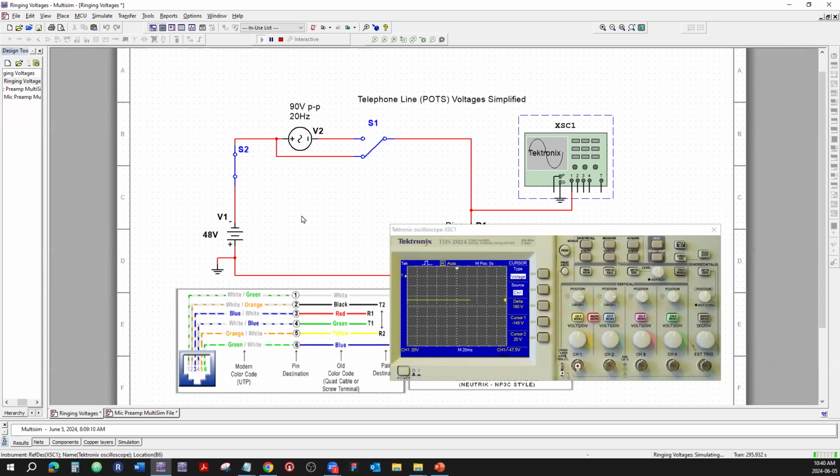So you could make announcements or general announcements using any phone that's connected to the system, just by picking up the handset and punching the feature number or the button that says page, and the signal will be transferred from the telephone system onto the little mixing board, which is connected to maybe an amplifier, which is connected to paging speakers or horns.